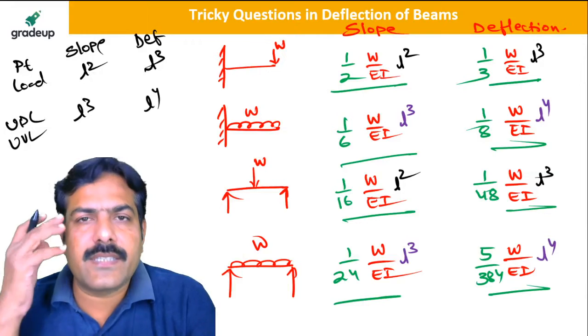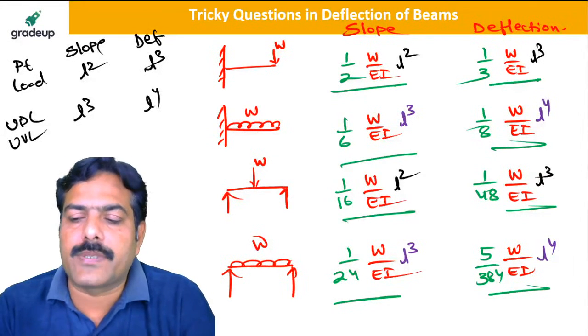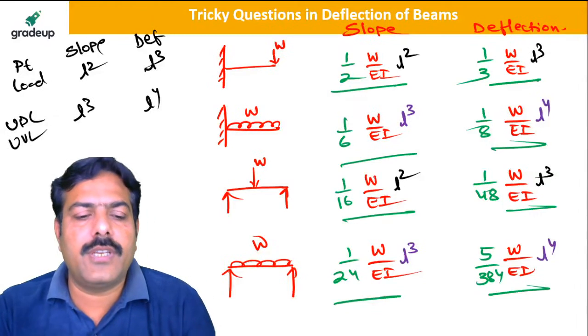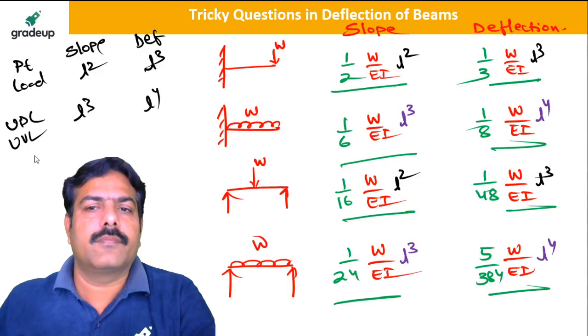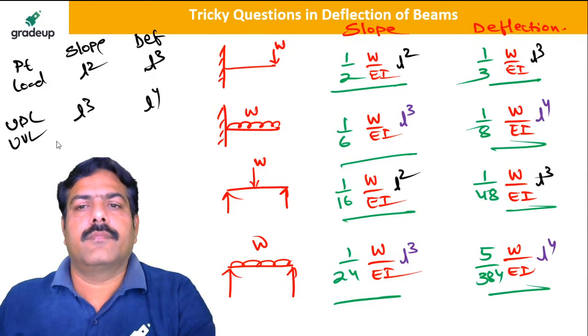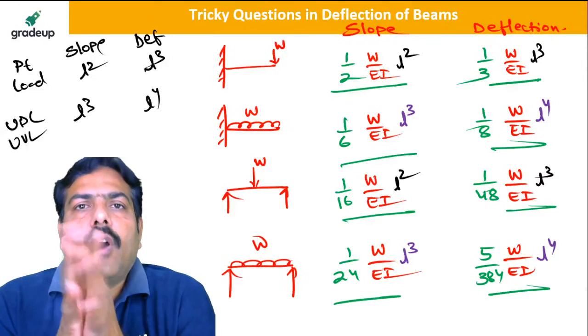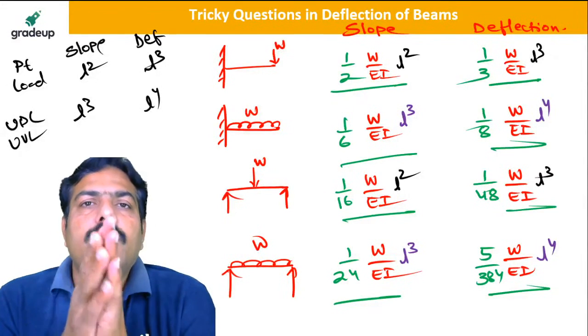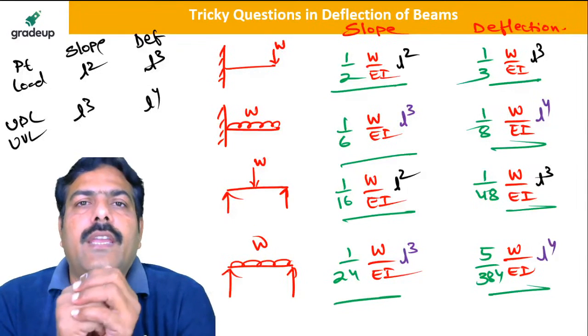So, my dear friends, now I will just brief you about the shear center and then we'll go for some problems. Now, can you tell me what do you mean by shear center? Somebody asked me the question about the shear center. So generally what happens is, if it is a rectangular section or a symmetrical I section, you see that there will not be any twisting because of the loading given on the beam.